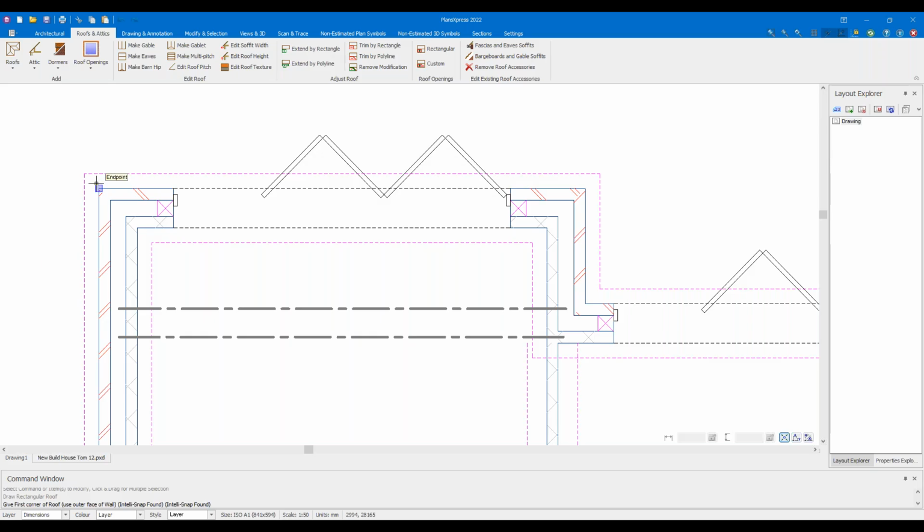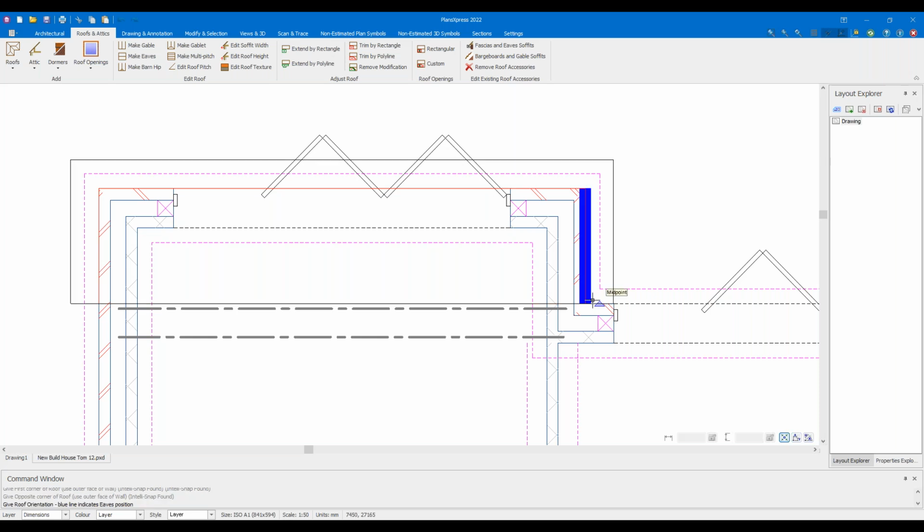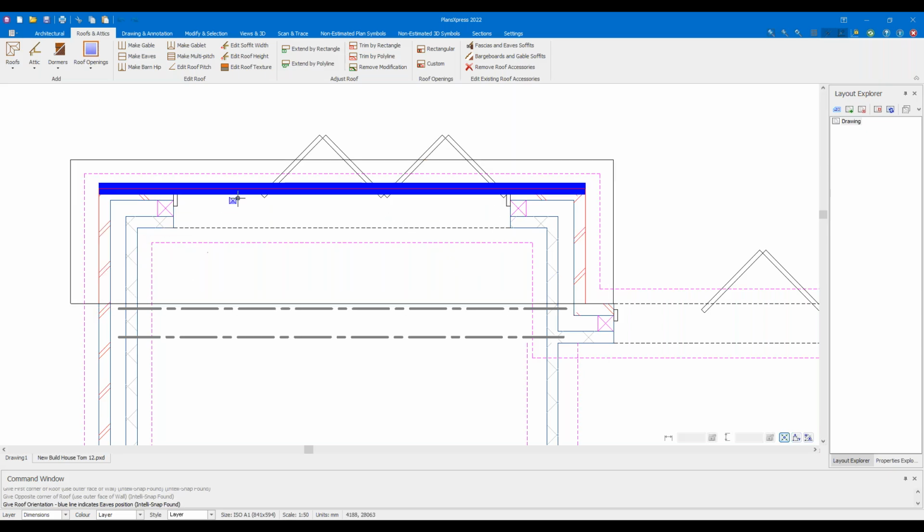So I'm going to go to the top left, left click once, and then start moving the tool so I can see it forming. You should see there a red box appear. It's following my mouse. And I'll go to this internal corner just there. It's actually illustrated on your document. That being in line with the wall and the wall above, when I left click, should now give me a preview shape of the roof plus where it's overlapping.